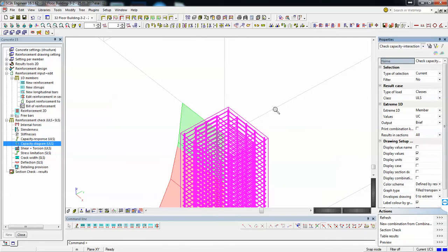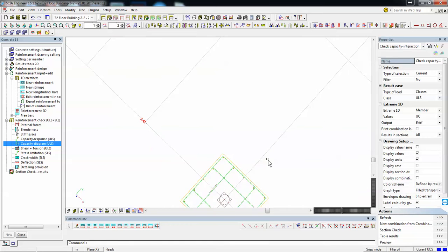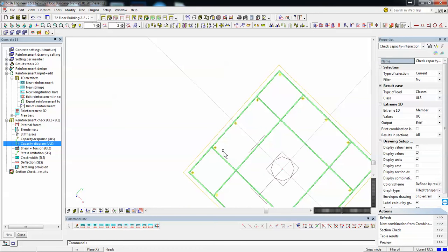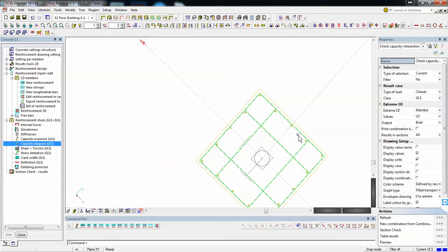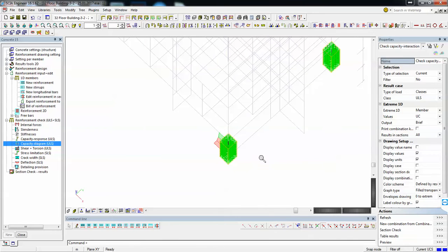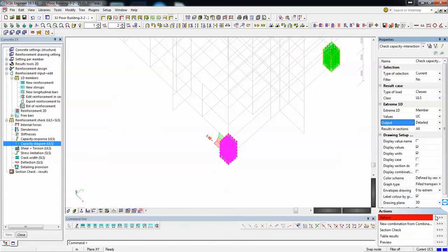Okay, it's still not enough, and I can change the number of rebars. It's okay to do this because we have a lot of space here. Also I can check how it looks from a detailed point of view, so I'll go to detailed, to see where the problem is, if the axial force is too big or it is just a problem of placing more reinforcement.